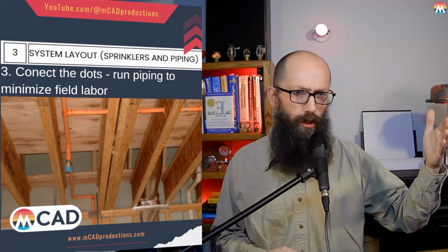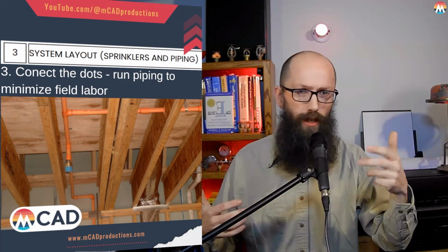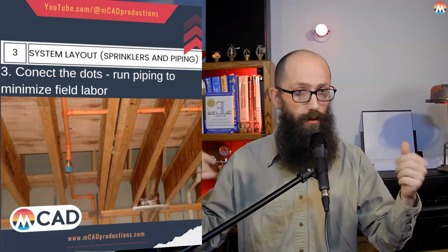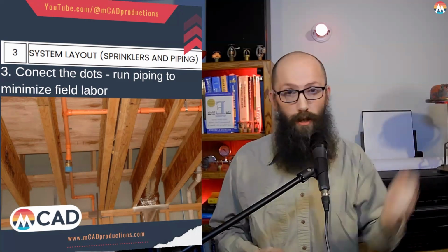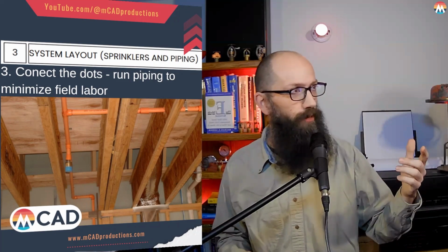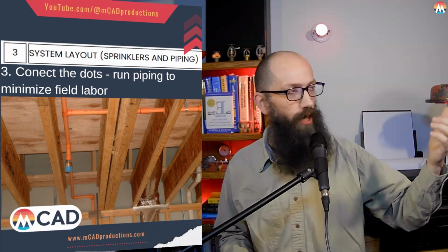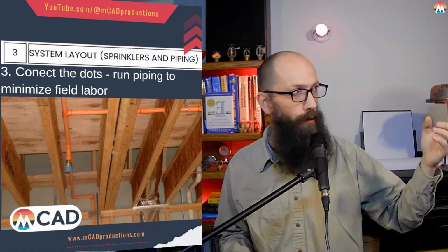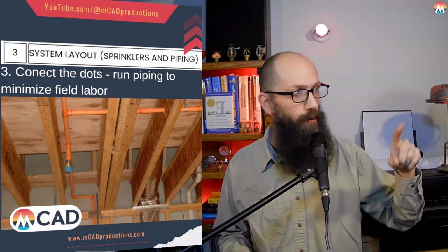If you look at this picture, you can tell there's obviously free space if we go between the joists, but if we go through them, we have to do some drilling. And it's hard to tell from this picture, but there's a coupling in the middle of that. The reason there's a coupling is because it's too hard to stuff that long of a pipe through those holes.